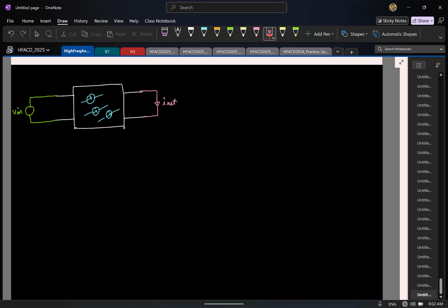But one nice thing is, the input signal that we apply is a small signal, and so are the noise current sources. Their amplitudes are going to be very, very small. So although your network might be nonlinear, for small signals we can approximate it as a linear network, which means you can nicely use superposition. To find only the contribution of the noise, what can I do to the input? I can de-energize the input, so the input is shorted. Now I'll be able to compute only the noise.